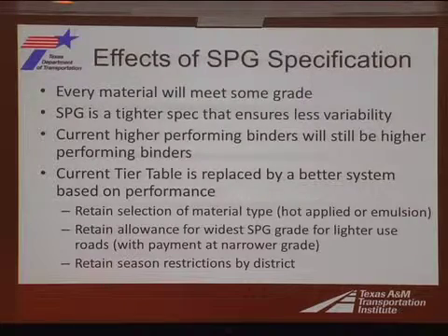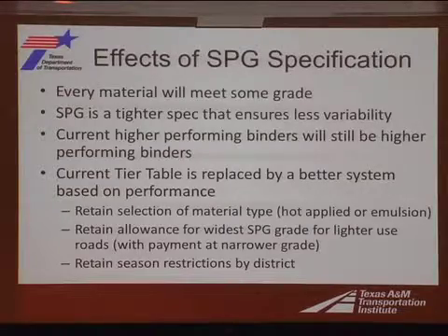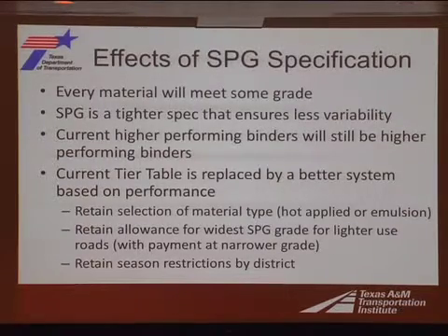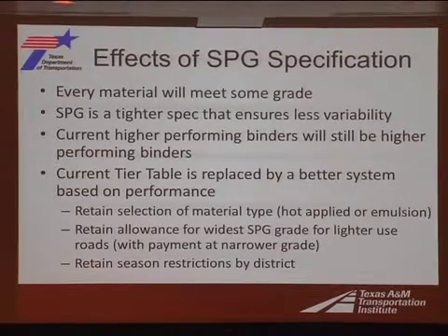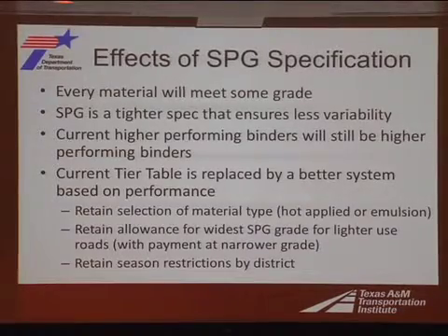High-performing binders will still be high-performing binders. Amy mentioned the phase angle, which is the parameter we use to get polymer in the grades. We know that so far that is not something that's easy to fool or to sneak in an unmodified binder in place of a modified binder. And bigger modification levels help you get that wide grade range, that useful temperature interval that Amy has so much trouble saying.